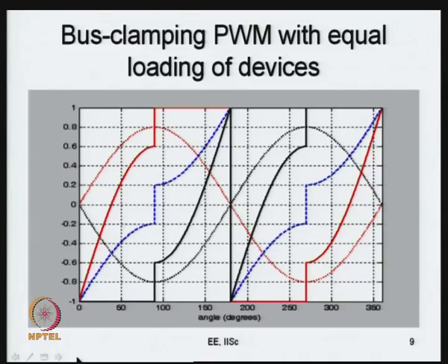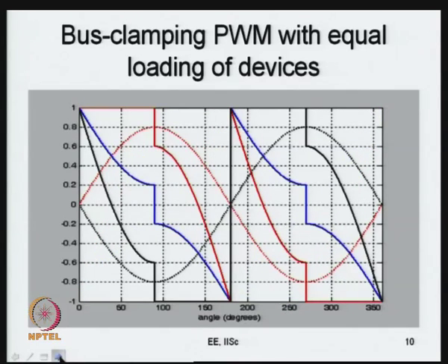So, you have to stop. What limits your usage? The top device limits your usage. How much power is being handled is limited by the top device. So, the bottom device is not fully utilized. That kind of a problem is not here. So, all the devices are equally loaded here. We will deal with this when we calculate switching losses in a much greater fashion now. This is another example of equal loading now.